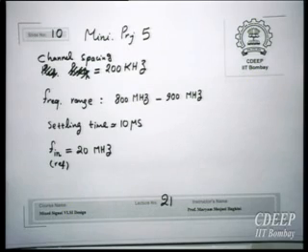You can use the same charge pump that you designed, but I don't recommend even that, because then you don't learn. Don't have the same frequency for your VCO, and don't use the same values of delay for your current starved inverter. The characteristic of the delay element for that current starved inverter, and therefore your ring oscillator, should be different. Suppose all of you use the same number of stages for the ring oscillator. To make the frequency different, your current starved inverter should be different.